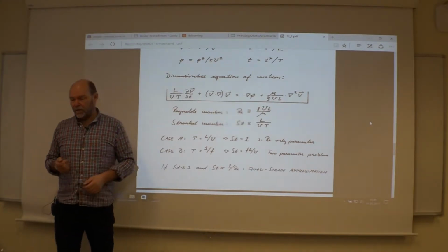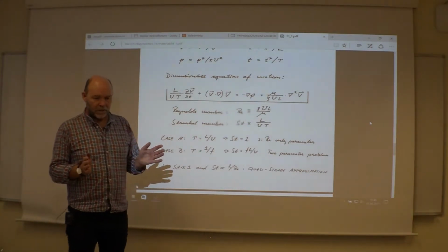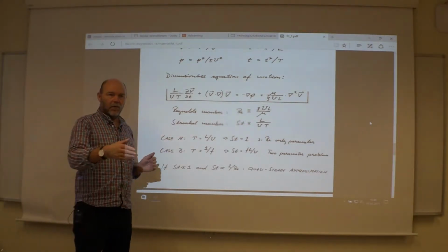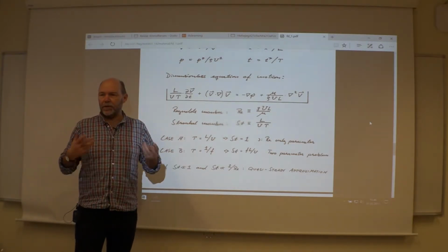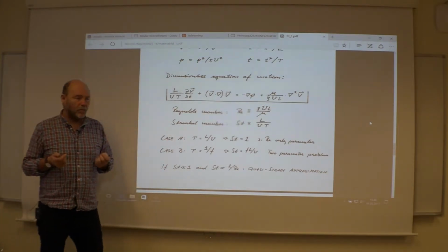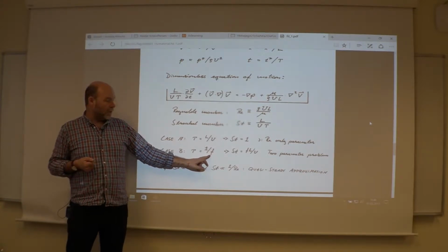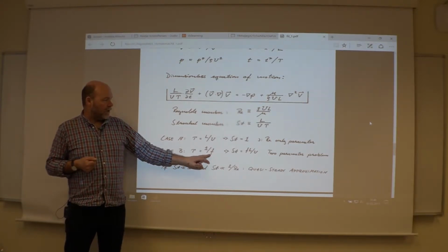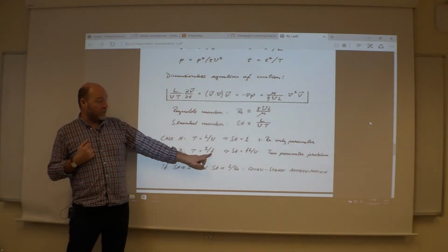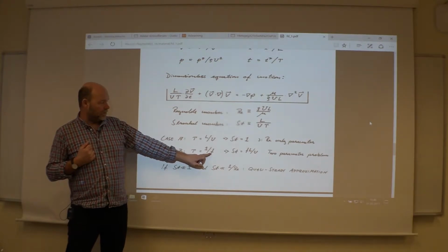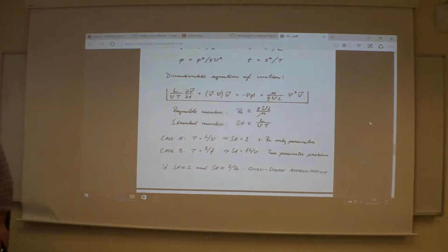Or it could be a flow, say around a cylinder, where we know you will have vortex shedding from each of the sides at a certain frequency. That's something that's built into Mother Nature. That's not something that we can control. Then this frequency is built into the problem by Mother Nature. And then definitely, yes, we should use the Strouhal number. The problem might be if we don't know the frequency, okay, then we can be in trouble. We'll see more of that later on.